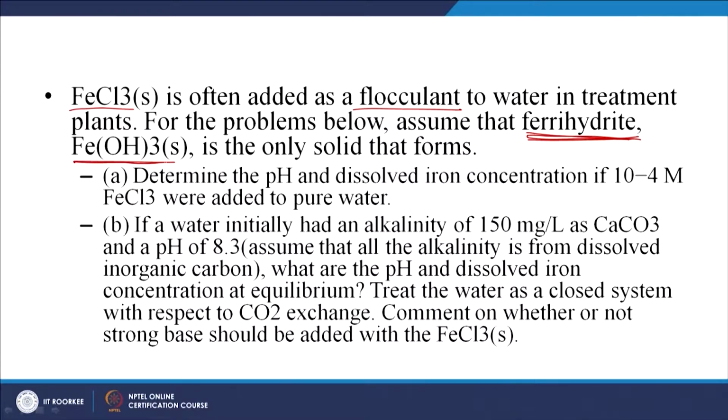For different types of solids, you saw that you had different solubility products. So unless you choose the relevant solid, or approximate it based on experience, you cannot arrive at the right answer. In general, as we discussed earlier, the amorphous forms, which are the most soluble forms of solid, are formed first. Ferrihydrite is a good enough example. Within the time frames we look at in a water treatment plant for coagulation and flocculation, formation of ferrihydrite is a worthwhile approximation, and it is the only solid that forms.